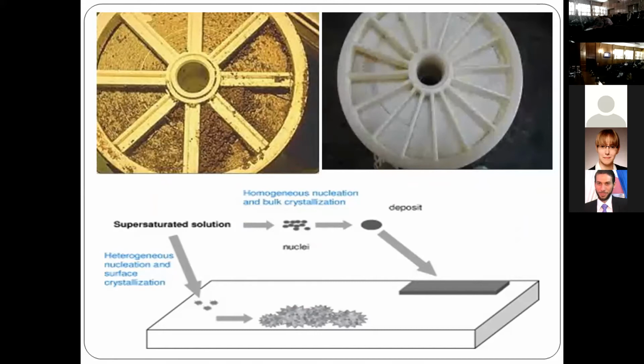Even water with SDI less than 5 and concentration of iron less than 0.1 milligram per liter can cause many problems and accumulate inorganic and organic scale on the membrane, leading to successive cleaning and eventual replacement with a new membrane. So the cost of treating this type of water increases.